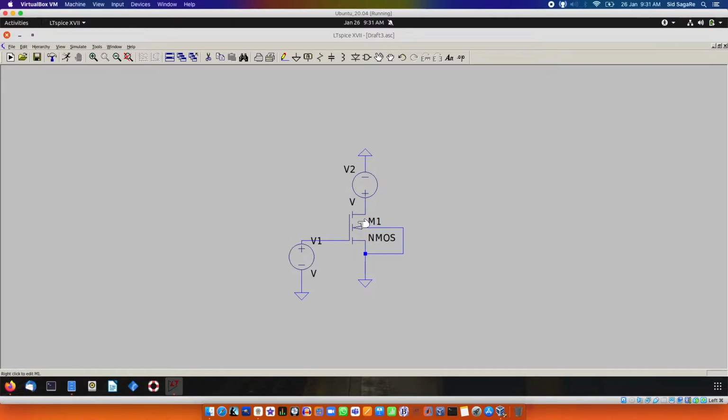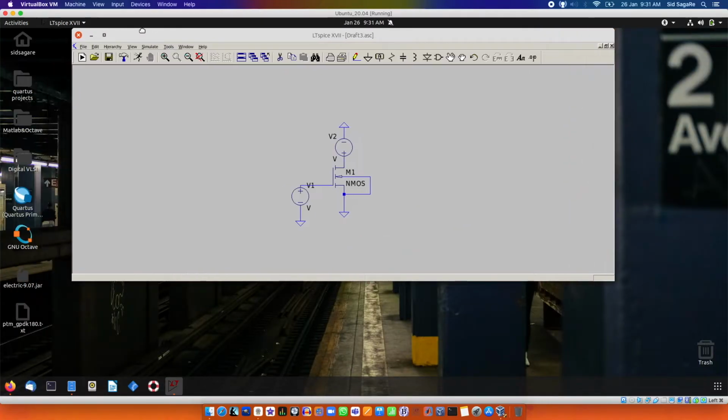Now I want this to be similar to the GPDK 180 nanometer technology, basically the one we use in the Cadence tool, in particular Cadence Virtuoso. So what I have done is I found a file called PTM180, which is more or less similar to the GPDK 180 and works for SPICE simulations. You need to save it in the place where you save all your SPICE folders. Basically, it's your C drive, users, the username, and my documents. Let me show you once.